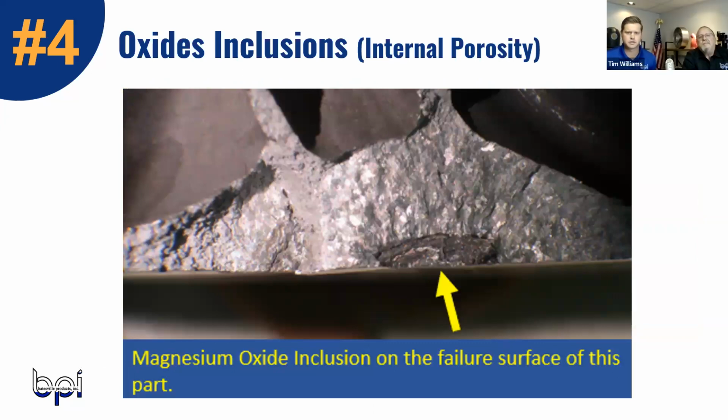Ernie, can you talk a little bit about what this picture is showing here? This is just a magnesium oxide inclusion that formed at the chill face. Is that correct, Brad? Yes, absolutely. And one of the unusual things about these types is it actually had a skim over it, almost like a flake that you could pick up to see what was underneath of it. Again, just an oxide that's filmed. Brad, is this related to the two mold faces, two metal interfaces coming together? No, I don't think so, Ernie. It's probably more related to when you're adding more mag to your melt, of not distributing that evenly, so you have an area that's enriched in magnesium. Yeah. And this would go to the point that if you're making an alloy addition, you have to make sure that you get it plunged and thoroughly distributed through the melt.